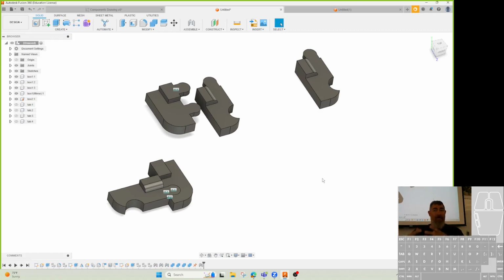And that's why we can test it here, do a 3D print. Make sure it works there, and before we go and actually cut metal. Because even though the 3D printers take a little bit more time than just cutting a piece, sometimes cutting a piece is way faster than 3D printing something. But if you're taking the programming time and the machine time, it's still sometimes faster. Because if we're doing a print here that maybe takes 3 or 4 hours, when you can program it real quick, if it's something simple and you can cut it in an hour.